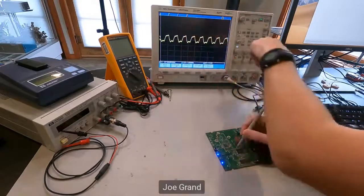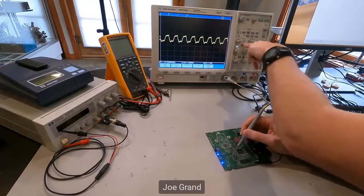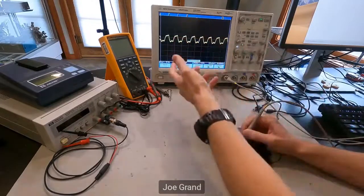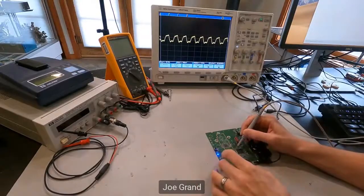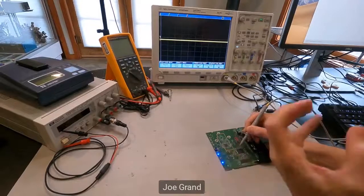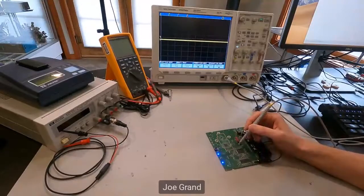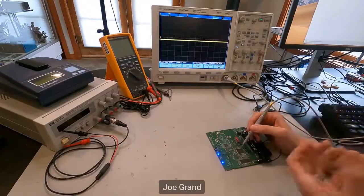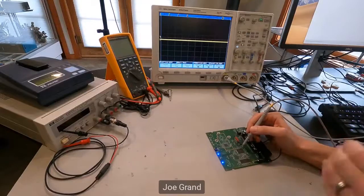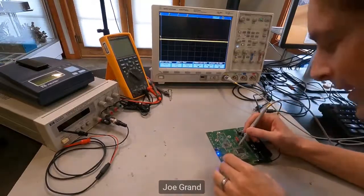So it looks like some sort of clock signal. Let's see, can I do a quick measurement? It's a 40 megahertz clock signal on the system on a chip, which is the main chip that's running. So maybe that's the heartbeat driving the system. That might be useful to know if we want to do some sort of clock glitching or fault injection later on, because we can inject our own glitches, or our own heart palpitations, into that heartbeat.